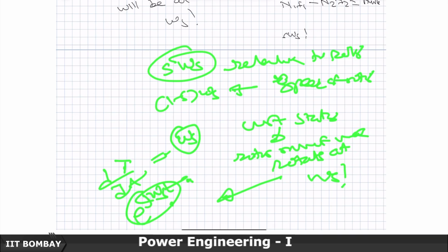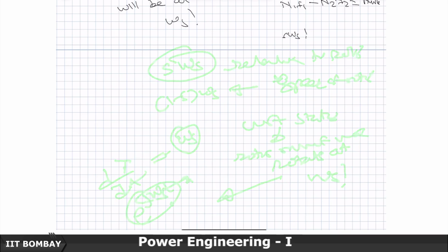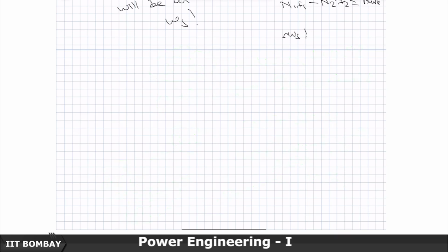So if this rotor MMF wave creates voltages at frequency omega s in the stator winding, what is the frequency of the current in the stator winding? It will still be at omega s. So the reflected currents of the rotor will be at synchronous frequency on the stator side.